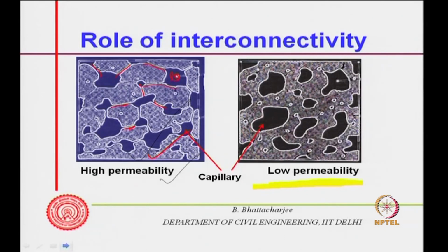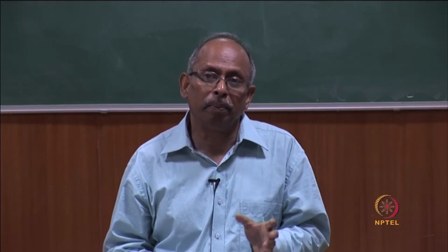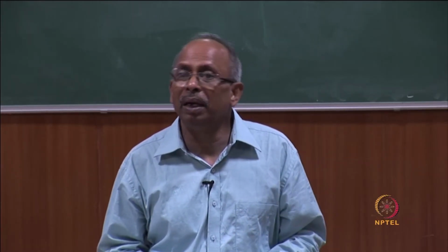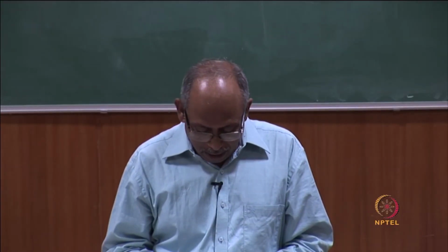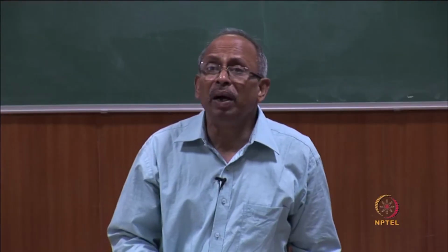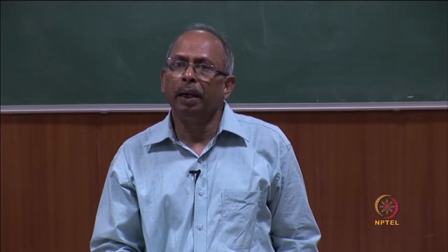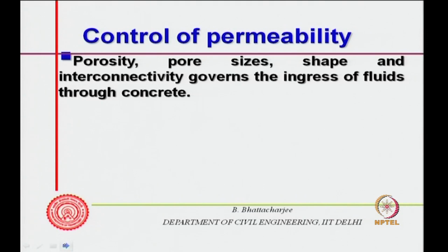Therefore, curing must also play a role, because if you do not do the curing, capillaries will not be segmented. I mentioned this when we were talking of curing. Minimum curing has to be done related to capillary segmentation. So, this gives us certain understanding related to permeability. What we have seen so far is that permeability depends upon porosity, pore sizes, shape, interconnectivity, and this all governs the ingress of fluid through the concrete.